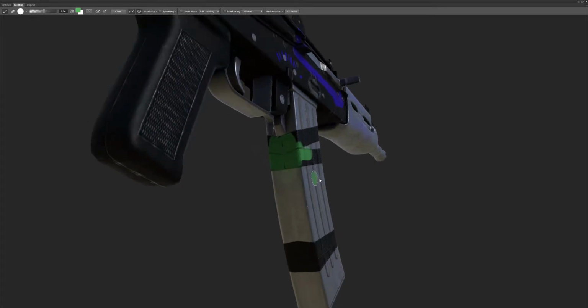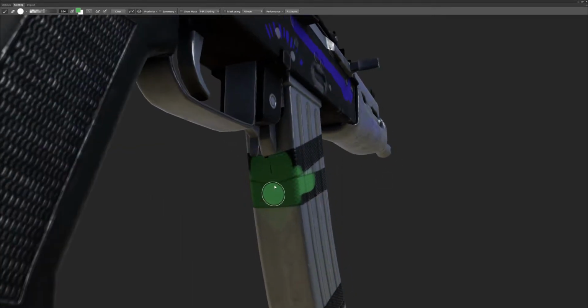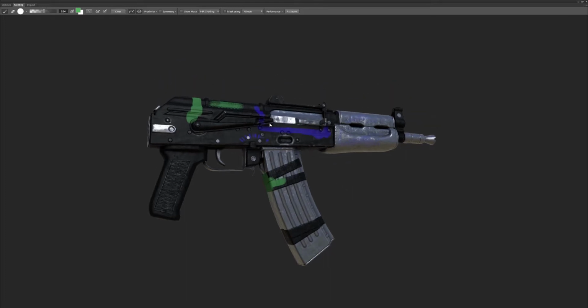What that does is when you're painting, you can see how at the UVs there's a little seam happening there. It's not really there. It will fix it when you stop painting, or you can just hit this fix seams and it will get rid of that unsightly seam.